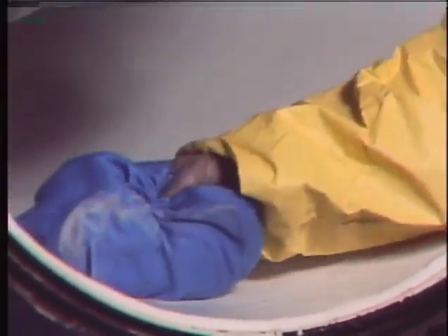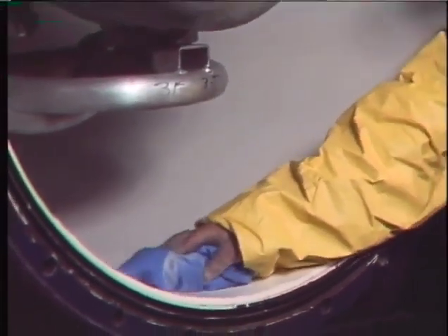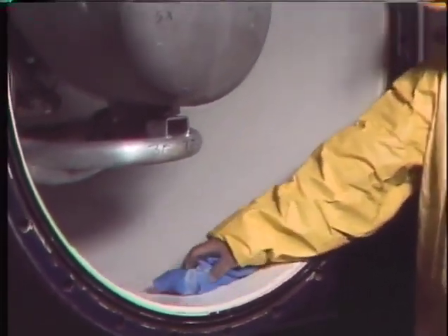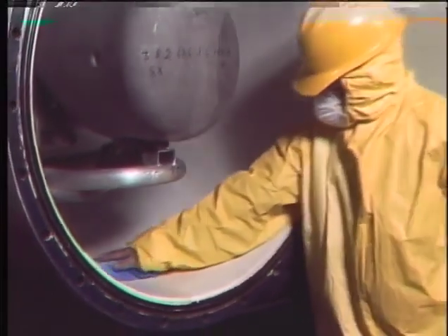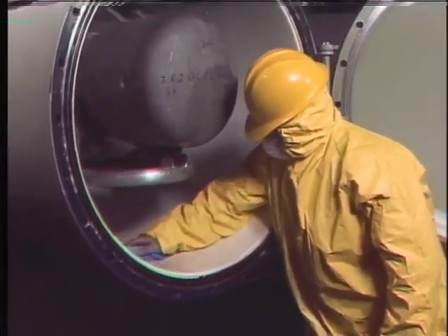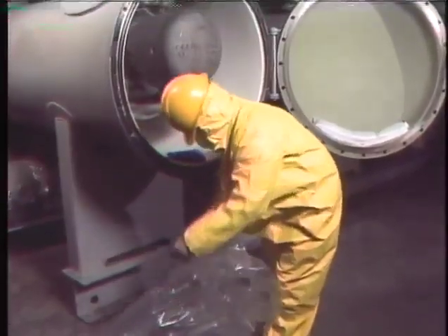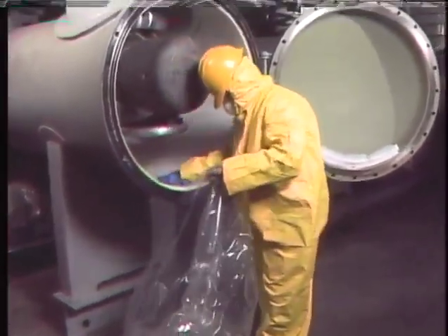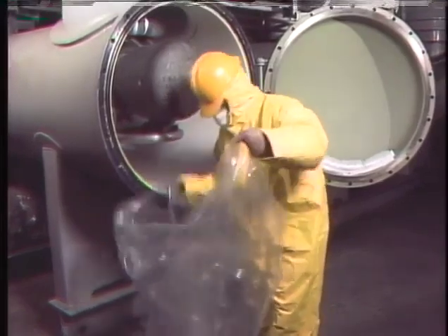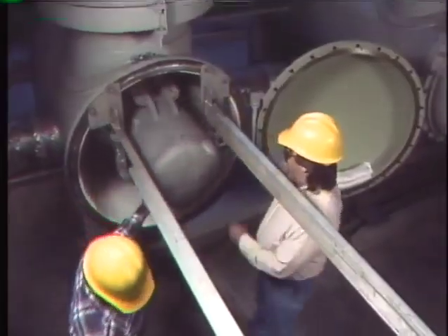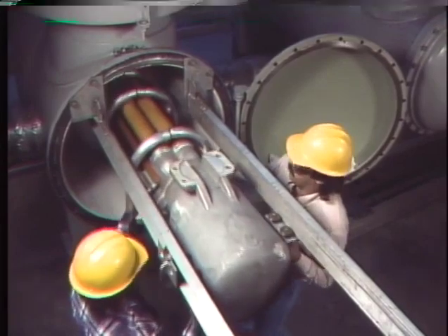After the breaker has been ventilated, the powder should be cleaned out. Besides being toxic, the powder absorbs moisture when exposed to air. Moisture reduces the dielectric strength of SF6 gas and can affect the ability of the breaker to extinguish arcs. When the powder has been thoroughly cleaned out, all rags and protective clothing are disposed of according to company policy. Then the breaker can be inspected and serviced.